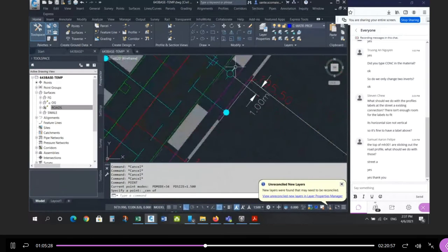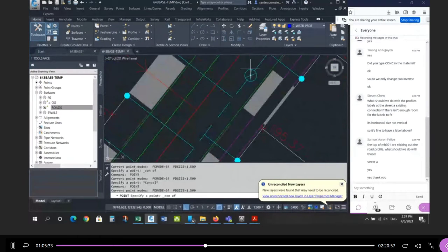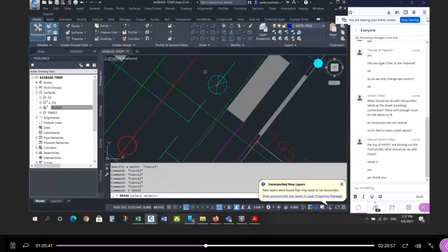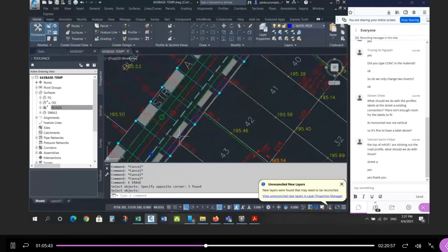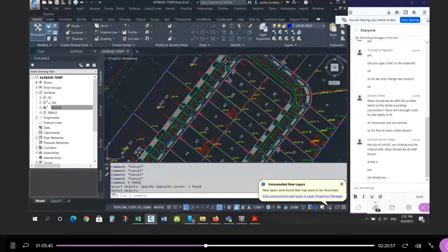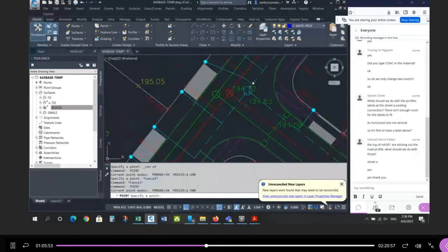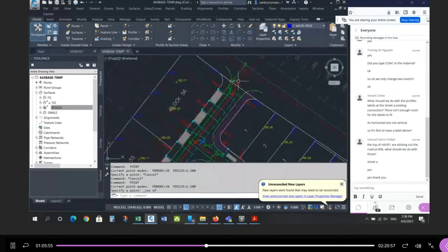And I'm going to move along the water main. Oh, here's a hydrant. Center. There's where my hydrant is. Oh, here's a valve box. Center. Good. I'm going to use this one. I drew two because I wanted to check. Yours had to be somewhere between these two. So I should only have one, so I'll use that one. Here's another hydrant. So point. Whoops, point. Center. There's my hydrant. Here's my valve chamber at the intersection.